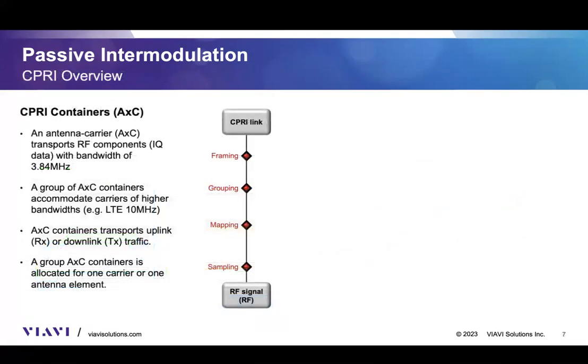Right, so I'm going to spend just a little more time here because it's important to understand a couple of aspects, and those aspects are going to be creating some challenges for 5G, or for that matter, for any new radios. And let me just briefly describe a new radio. New radio, it's those that are handling multiple carriers or multiple bands. So we have low, low, high, high as an example. There are single band multiple carriers, but also we have dual band or tri-band with multiple carriers.